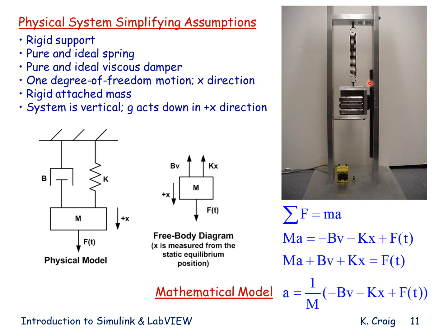So I have a real spring, a real linear bearing, a real support, real mass, and I need now to create, using engineering judgment and simplifying assumptions, a physical model of this physical system. So the assumptions that I will make are that, one, the support, the base plate, the vertical support structure is rigid. As the system undergoes its motion, it does not flex. It is connected to ground, so all measurements made with respect to this support system are absolute, measured with respect to ground.